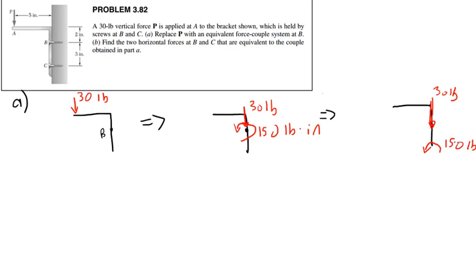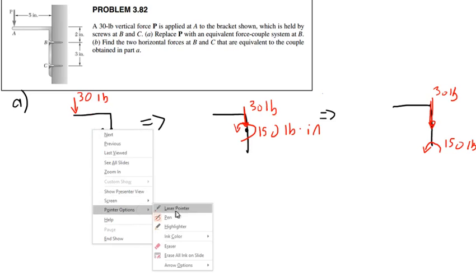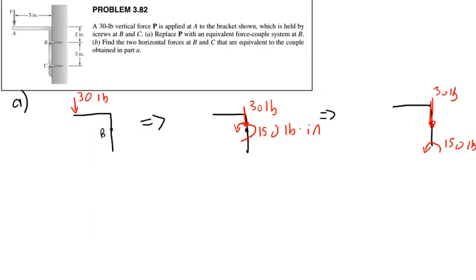I don't understand the whole 30-pound being directly. That's like if I put 30 pounds on a bolt, rather than 30 pounds on the end of the lever. Okay, what's happening here is, let's go back and review this. What don't you understand exactly? How's the 30-pound creating a 150-pound-inch moment directly on it, not using the lever arm? It's not creating that. All we're saying is this system is equivalent to this system.